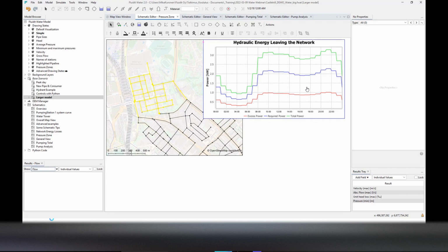What this tells us, I think this is a result or a way of looking at the energy saving potential. Obviously, this doesn't directly tell that we can just lower the pressure. That might lead to trouble in one place. But this tells us that we can easily look at different parts of the network or the whole network, and we can see the energy saving potential. Is it there or not? And if it is, then we start digging deeper into it. If it's not, we can directly see that, hey, this area of network, there's not much potential. Let's not waste our time and energy on that.